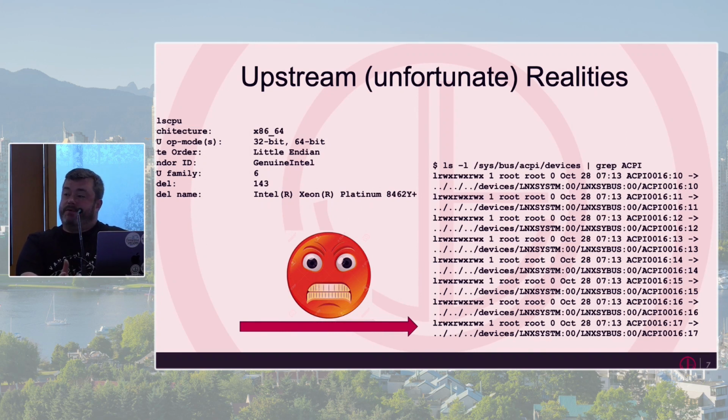So this is actually the root of how to support type 3 devices: you need this table to then build the hierarchy to actually have a /dev/mem device instantiated. If you look really close at the launch marketing for Sapphire Rapids, it says, hey, we don't support type 3 devices. We support type 2 devices. But you can make a type 2 device look like a type 3 device. So this is part of the reality that you can deal with: there's a BIOS entry in Sapphire Rapids BIOSes that says support legacy for type 3 devices. And I'm like, it's a brand new protocol. Why do we have something called legacy? Anyways, you can tell that I'm a little bit passionate about some of these things.